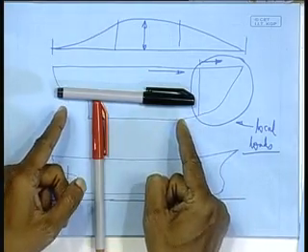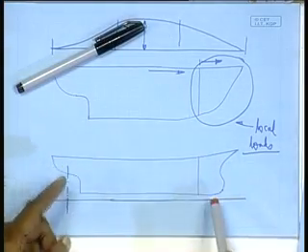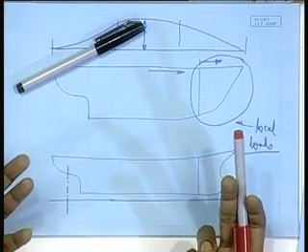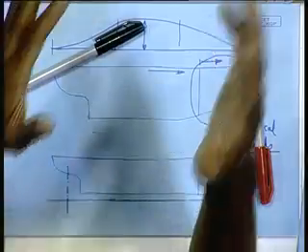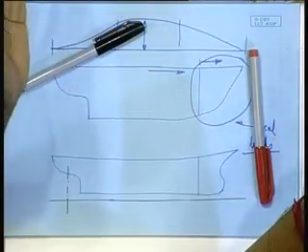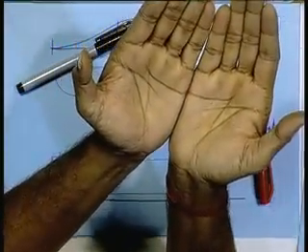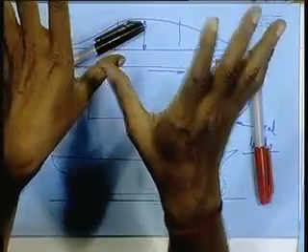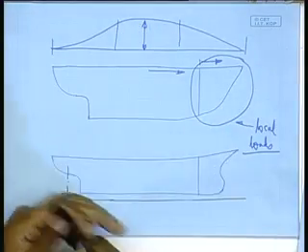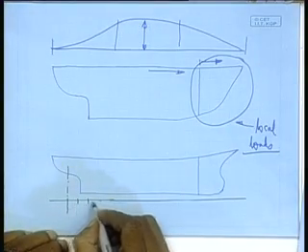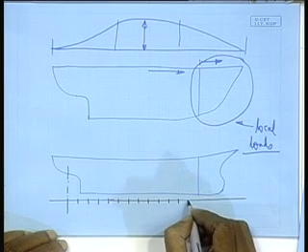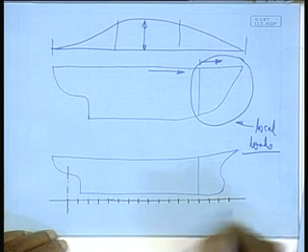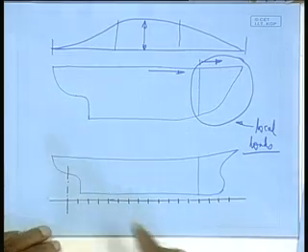Not only that, this entire hull, as we have seen, is composed of stiffened panels. That means individual flat or curved panels, and then subsequent units and blocks will be constructed. One will be joined to the other. So, how do we know which one, where, and at what distance? The primary reference is the frame spacing. That gives me the reference of the location of my stiffeners, as well as the entire definition of the vessel.